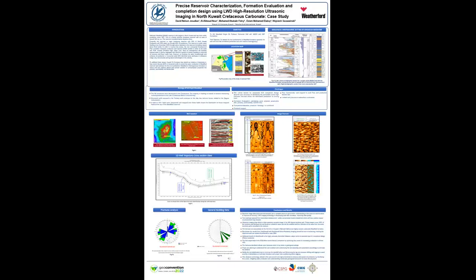Moving to the analysis of the fracture and the bedding, in figure 9, here is a Dip-Azimuth Schmidt plot showing the statistical analysis of the composite fracture, which reveals a fracture trend to the northeast-southwest strike. The Dip-Azimuth plot for the bedding data shows the bedding surface trend to southeast, and the identified bedding surfaces have a dip angle of less than 1 degree.